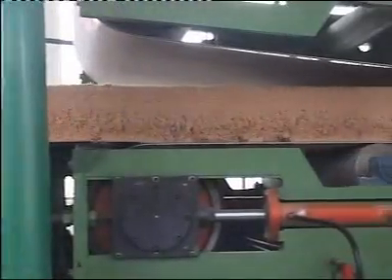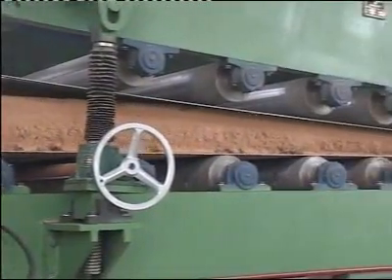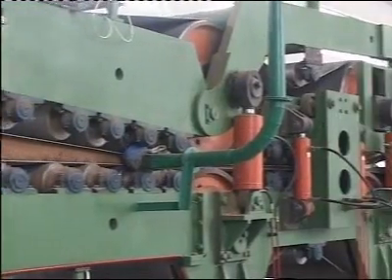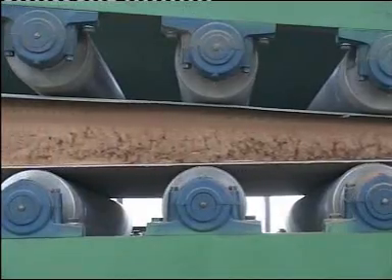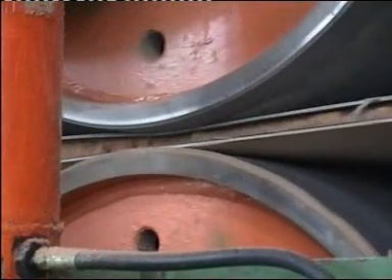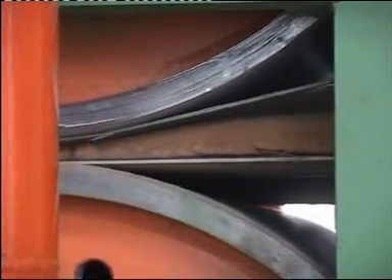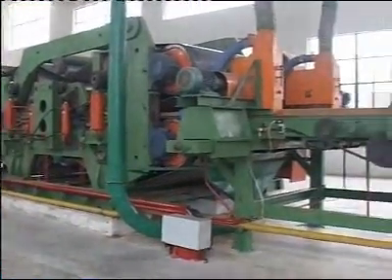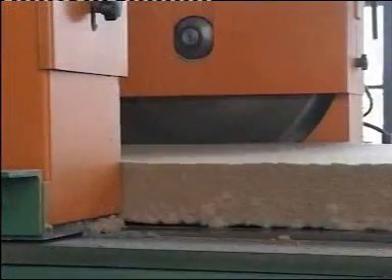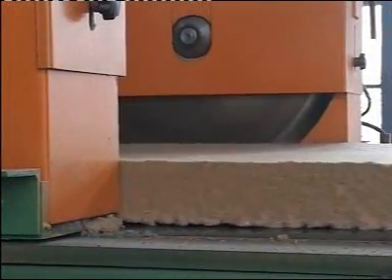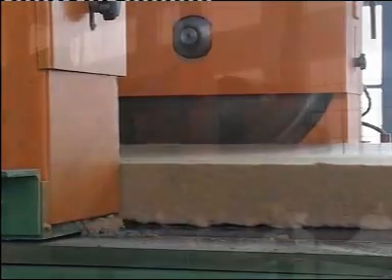The already formed mat is firstly transported to pre-press so as to remove the air in the mat to make mat with certain thickness and certain strength to avoid break and damage during the process of transport, cutting, loading, etc. After mat trimming saw, pre-pressed mat is trimmed to required weight and then cut to required mat length via transversal saw.